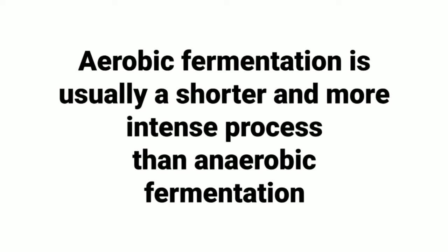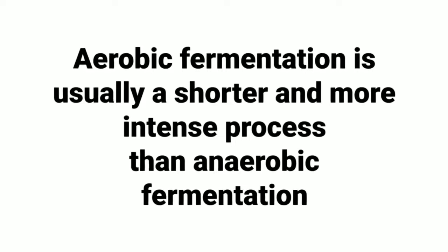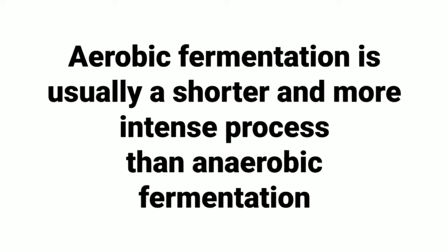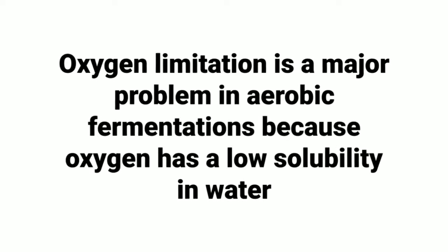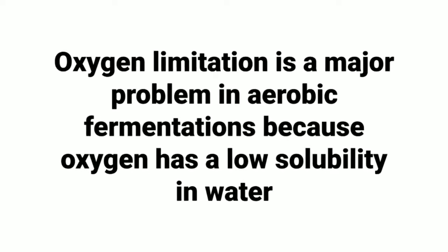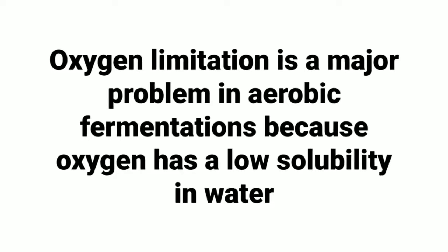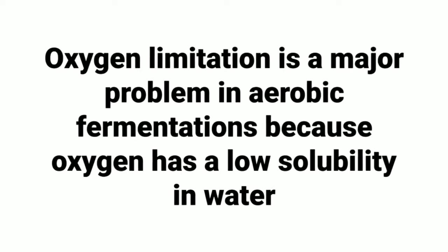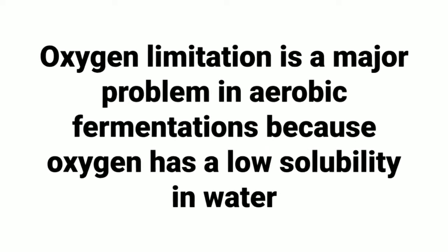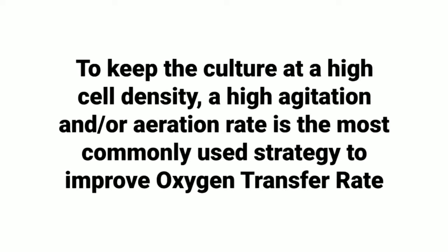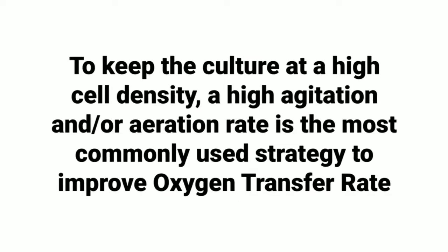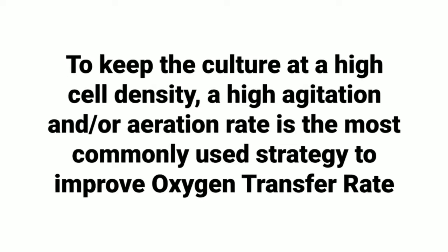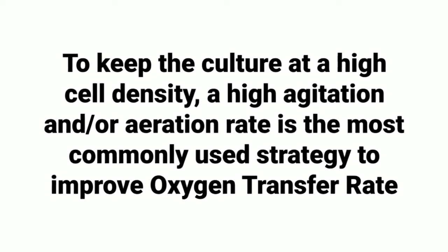Aerobic fermentation is usually a shorter and more intense process than anaerobic fermentation. Oxygen limitation is a major problem in aerobic fermentations because oxygen has low solubility in water. To keep the culture at a high cell density, a high agitation or aeration rate is the most commonly used strategy to improve oxygen transfer rate.